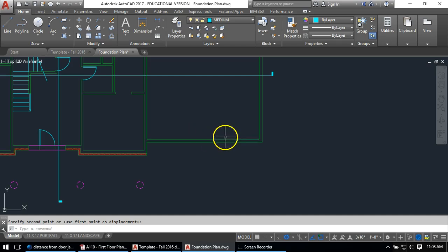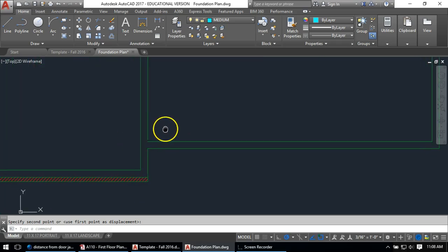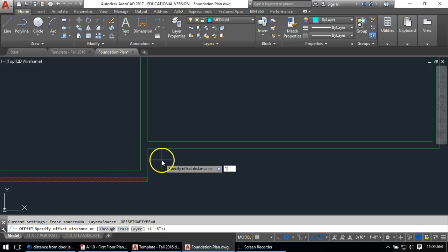Then down along this wall, there's actually some garage doors that are 108 inches wide each. Offset 1 foot. Oh, there's a little, got to fix that corner. Fill that corner together. Offset 1 foot clear. So I'm going to offset 1 foot and extend this up to be the jamb.